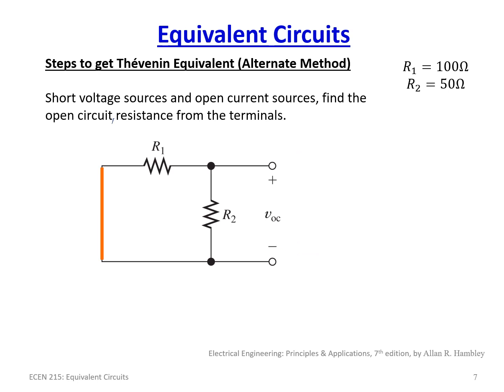So what does that end up looking like? Well, that looks to me like a parallel set of resistances. So we end up with R1 in parallel with R2. So let's take a look at that. What does that become? That becomes 5,000 over 150, because this is 500 times 100, using the formula for 2 resistors in parallel, over R1 plus R2, which is 150. So the formula for this, just as a reminder, is R1 times R2 over R1 plus R2.